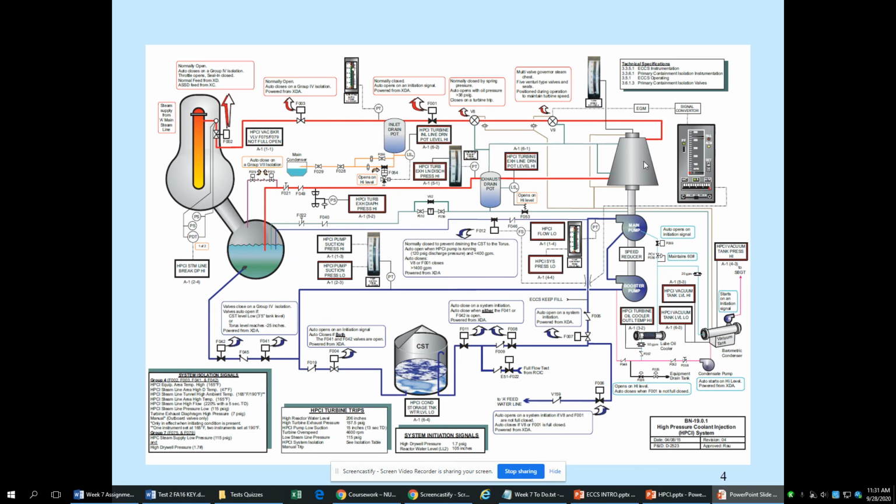So you can see attached to my turbine, I have a shaft, and that shaft is attached to a main pump and a booster pump. So I'm using 2 pumps together because I need to really push the pressure up. So let's look at the water side. It's going to take the water from the torus, which, remember, I just put some steam in here and it condensed. So this is a good cycle. It's going to be self-sustaining because more water is going to be coming in the form of steam condensing. So I'm going to pull the water off here. It's going to come through my booster pump, and that's going to push the pressure up. It's going to come through the main pump and push the pressure up even more, and then it's going to make its way back towards the reactor vessel. So there we go, back towards the reactor.